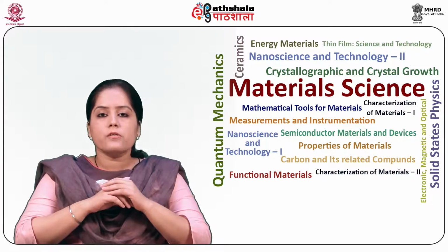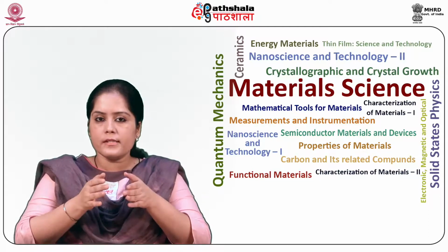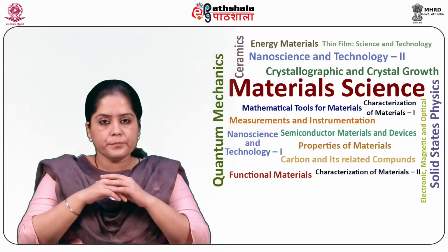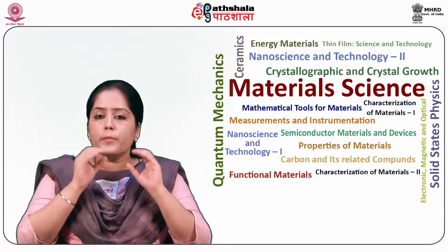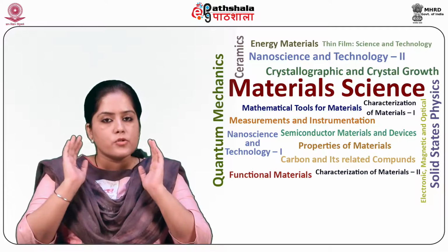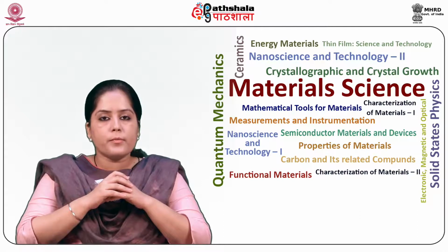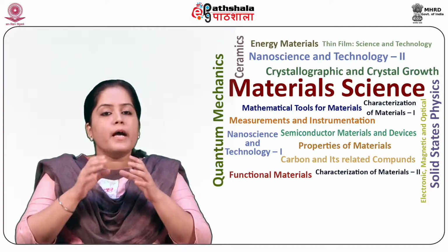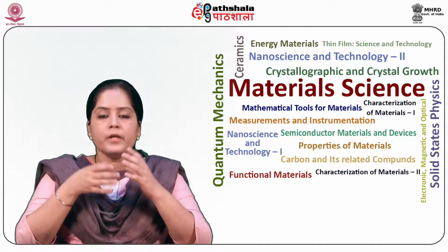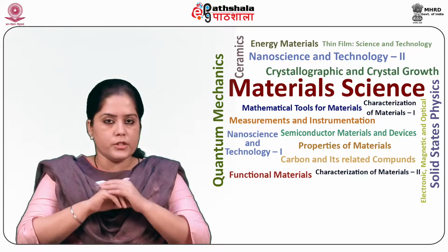The disadvantages of PLD are chances of non-uniform thickness and varied composition across the deposited film, as here the plasma plume formed during the laser ablation process is extremely forward directed. However, this problem can be tackled by rastering of the laser spot across the target material or by substrate rotation during the deposition.